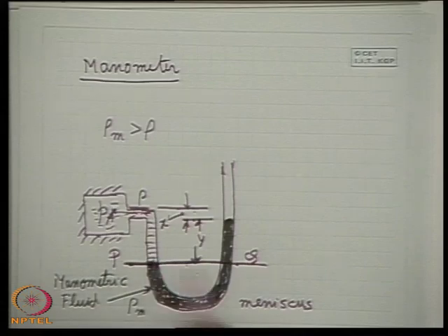That means pressure at this point is equal to pressure at this point, because these 2 points do not vary in the vertical displacement. See, the pressure increases if we go down here, and when you go up, pressure decreases. So ultimately these 2 points have the same pressure. That means pressure in the same expanse of fluid, you have to remember this very categorically, is the same provided they are not varying in the vertical displacement. That is, at the same horizontal level, pressures are the same.